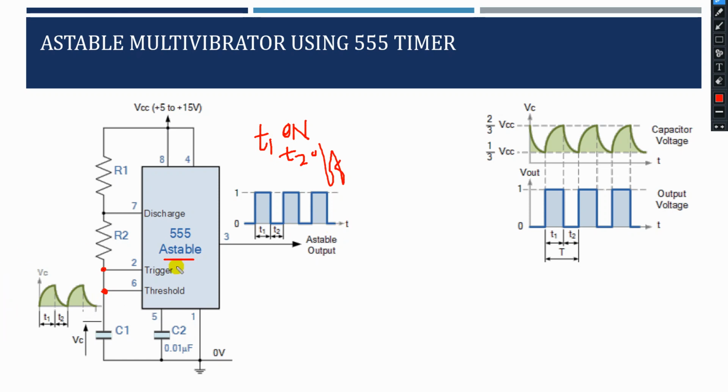So during each cycle, capacitor C, as we have noted as C1 here, charges up through both timing resistors, R1 and R2, but discharges itself only through resistor R2. It can discharge only through that resistor, because the other side of R2 is connected to the discharging terminal, pin 7. For charging it uses R1 and R2. Until the charge completes, your T1 will be on.